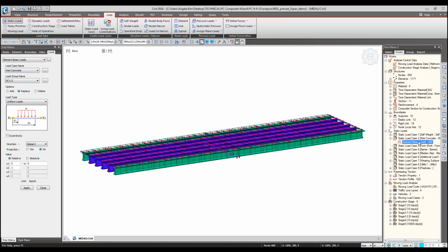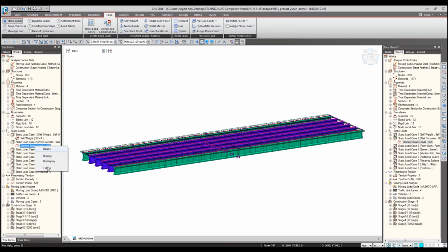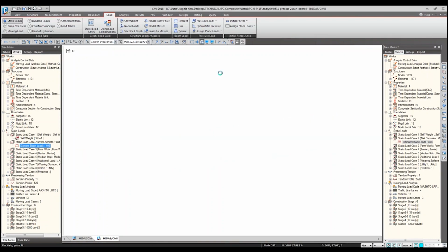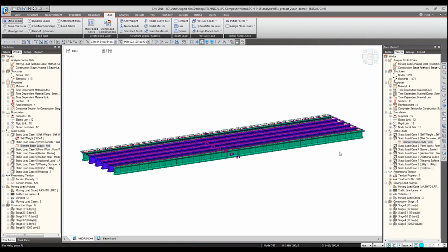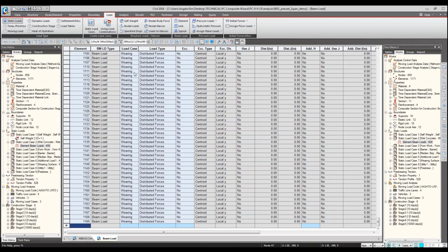Or if we already have a certain loading value, but the problem is to add a little more or take out a little more, you can either use replace, or if it works out by adding an additional value, you can also use add. So this is one way, by using the main functions in the program itself. And the second way will be fixing the data in the tabular format. MIDAS is a very graphical tool. You can see everything graphically, but it doesn't mean that you can't have the data in a table.